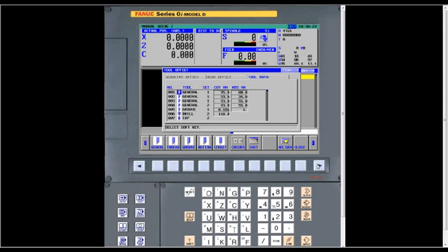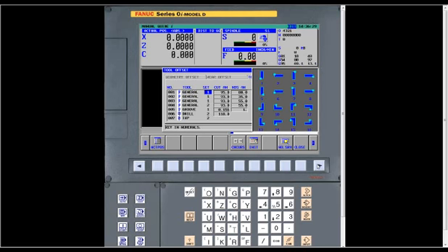Okay, in my tool setup here, on number 1, it's a general tool. That's the type. Then setting. As you can see here, it's got 16 different selections. This is basically for your simulation. What you need to do is look at the tool that you have in your particular machine and see how it corresponds to these 1 through 16, and that's what you need to put there. I've got a number 1 because, as I said, I know mine. It's an upper turret, 80-degree turning tool. And so that looks like a number 1 in these fields.